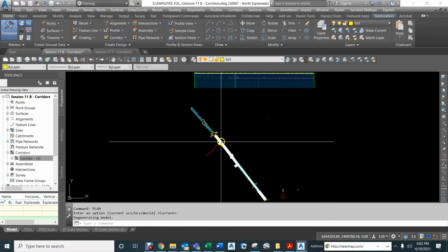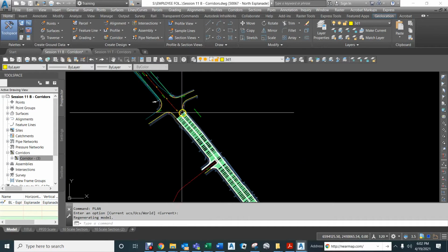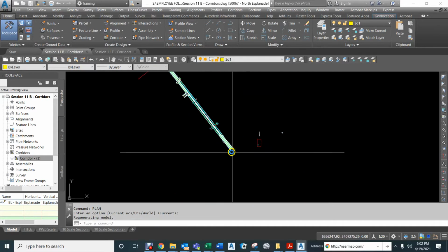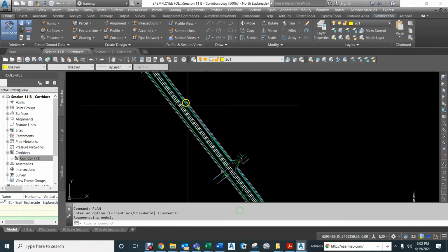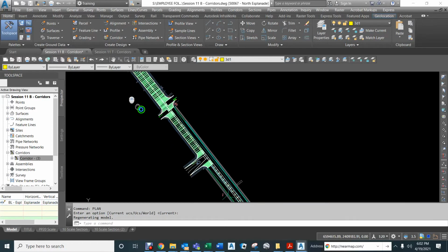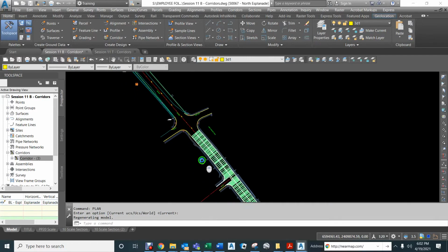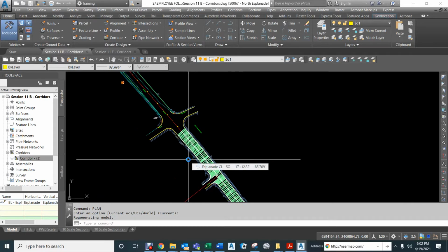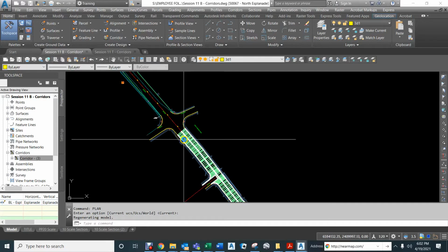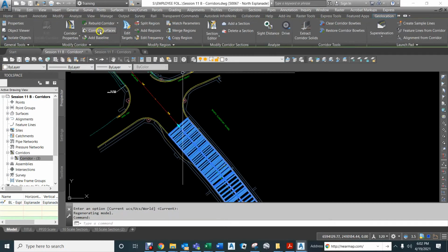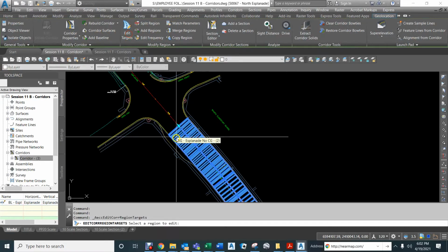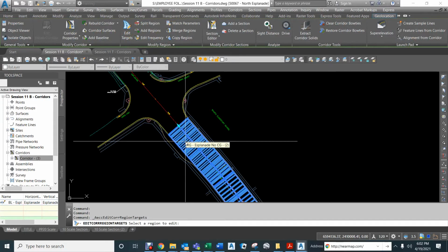So how we would do that, we've basically, from this intersection down to the bottom intersection, targeted all the existing lip of gutter lines that we put in there all the way up and down, only in the horizontal direction. Now what we're going to do is target those in the vertical direction.